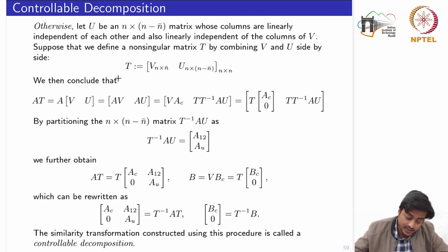So we just have constructed a T matrix given the matrices A and B. Okay, so this part is called the controllable decomposition. We will explore further properties. With introducing this specific T matrix, we have decomposed the A B matrices into controllable decomposition.